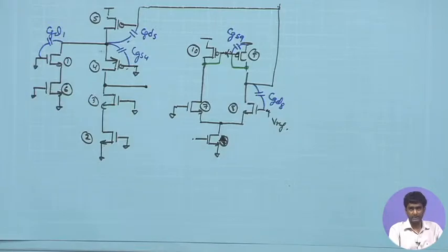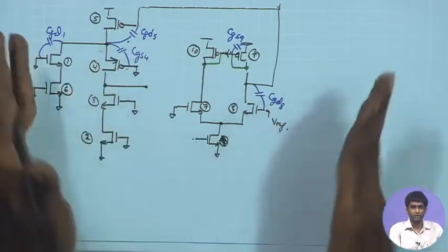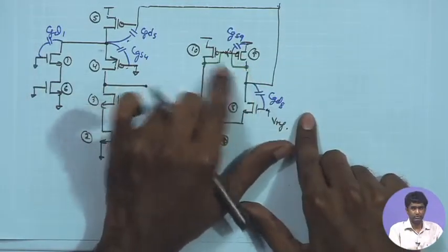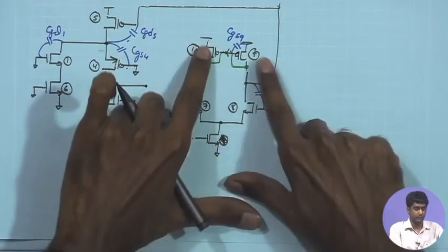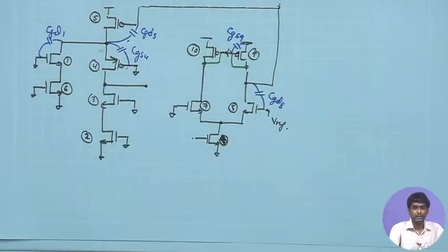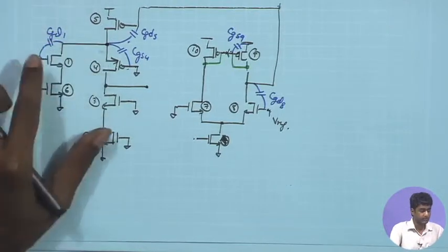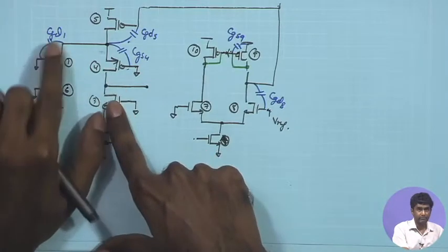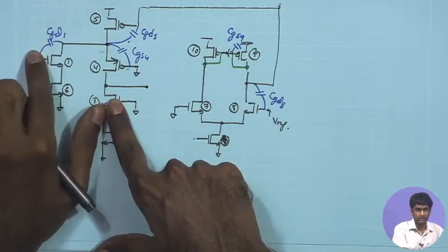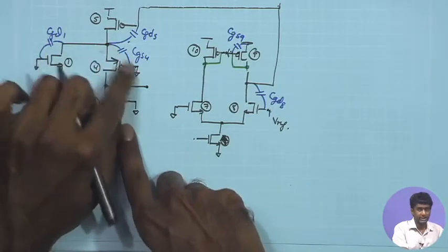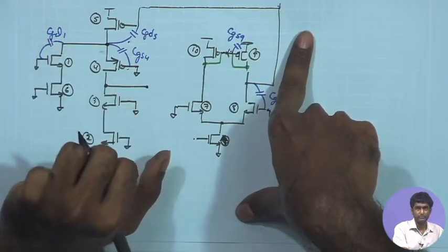So, in summary, these are the capacitances that we have. Remember that we decided to use a diode connected load for the error amplifier. So, both of them have a low impedance node over here, with impedance approximately 1 upon gm for these two transistors. If I look at the overall capacitance, we had the CGD of M1, whose gate is AC ground, therefore it appears directly between the drain and AC ground, not having Miller multiplication. Then CGS of M4, which is going to be significantly larger than the CGD values over here.